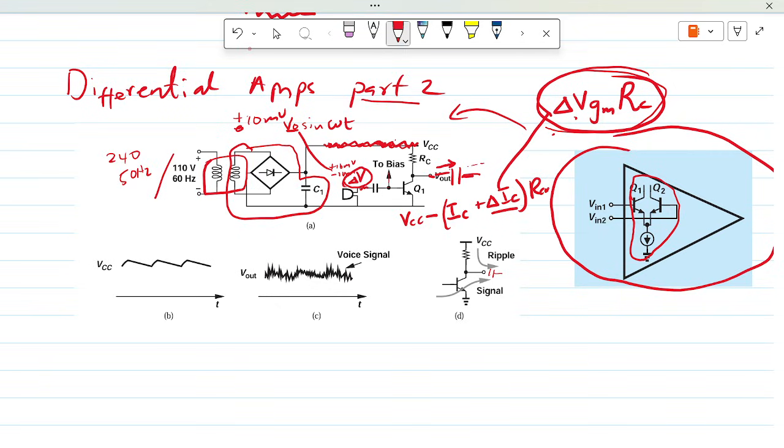Any noise in the cables or wires joining the microphone would also go through as high-frequency noise, and also go through to the outputs. So the output will look like the amplified input, that is the gain times the input plus any ripple noise. That is what we are going to see at the output after the capacitor takes out the DC part.